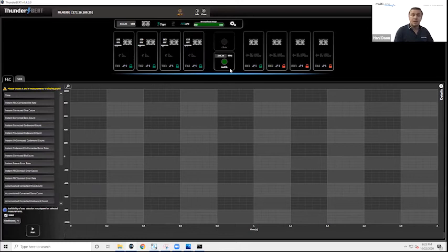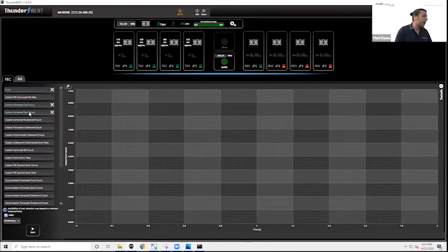Now, let's test that out. We also have 100 gig FEC and 200 gig FEC. We can get into that a bit later. Each different BERT we have offers different FEC encoding mechanisms. So now we're going to repeat our steps, not showing the pre-FEC statistics this time, but the post-FEC statistics. We have a really wide variety of measurements related to FEC performance that you can read more about in our FEC white paper, which is on our website, and I'm sure we can send that out later.